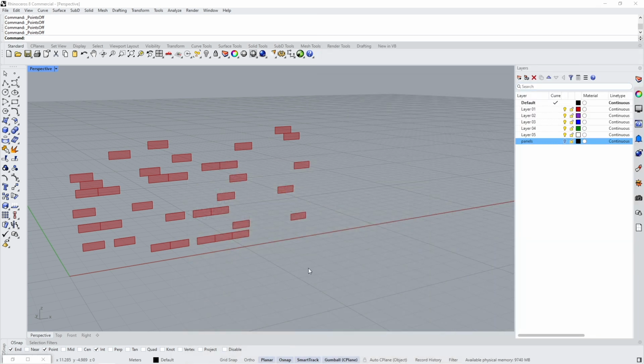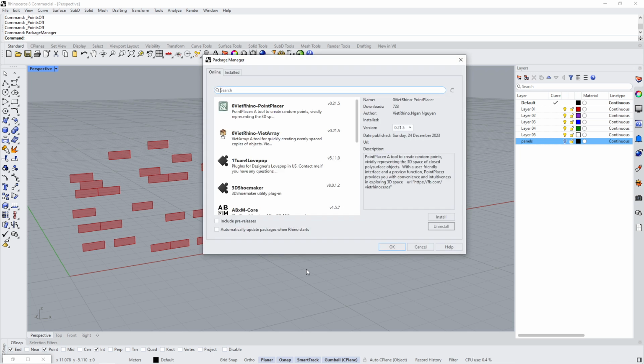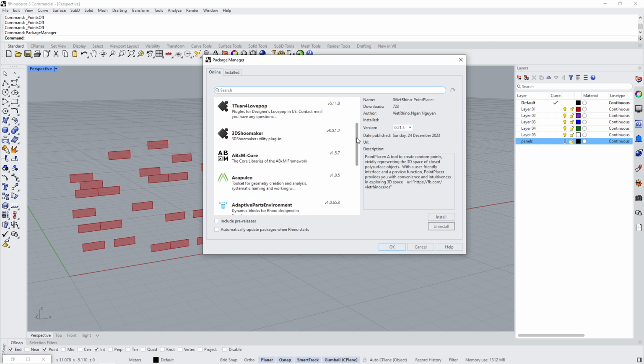And Rhino right now has a new way of installing plugins either for Rhino or for Grasshopper directly. So you don't have to copy files into your system directory and things like that. And the way to do that is going to Rhino and typing in Package Manager. Because the Package Manager, that's that new tool. And the nice thing is that you have a window that will pop up with a search bar where you can search for a lot of different types of plugins, right?